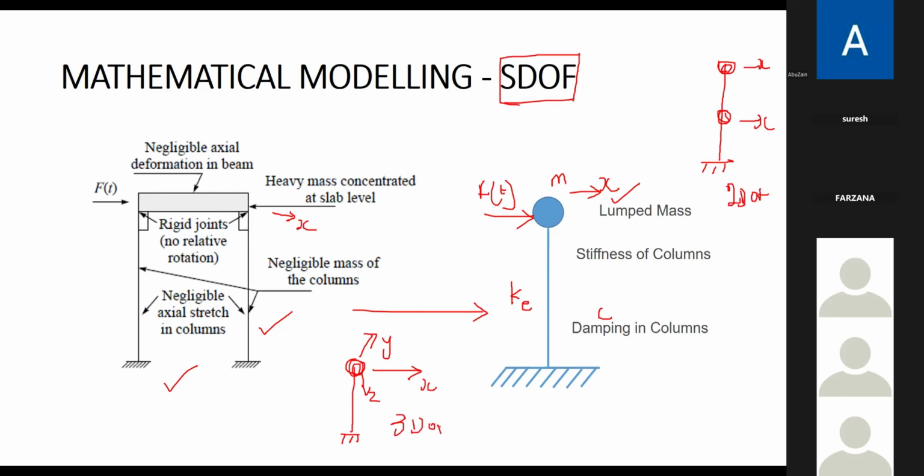So we have to understand what a single degree of freedom system and a multi degree of freedom system are. For our codal procedure, for our simplified procedure, we go only with this. But when we do it in ETABS, per node 6 degrees of freedom will be considered. Then only the torsion mode appears. In this case, you will have only the bending mode.